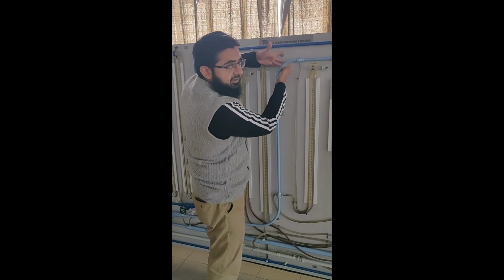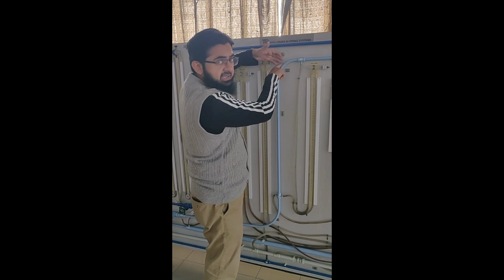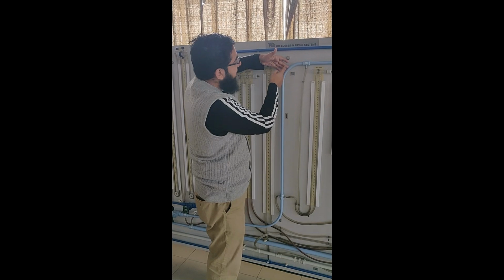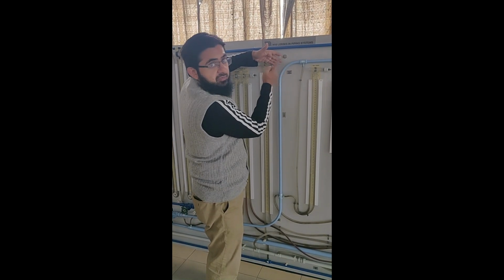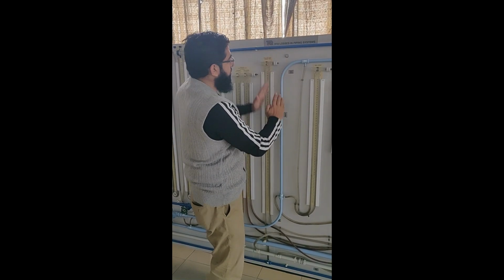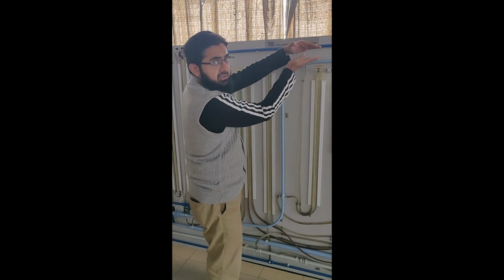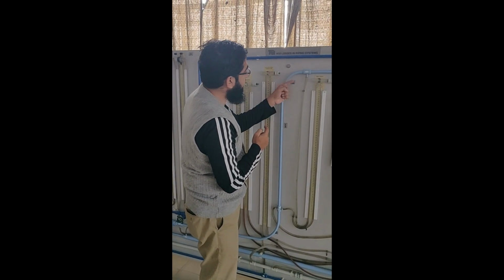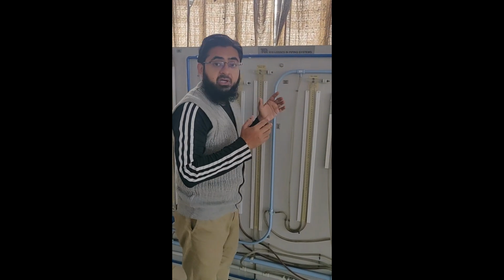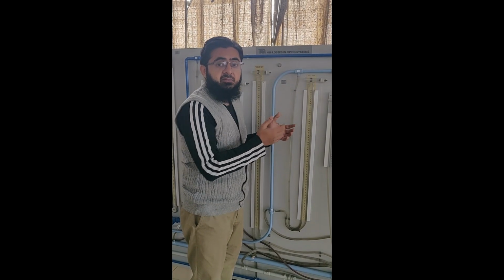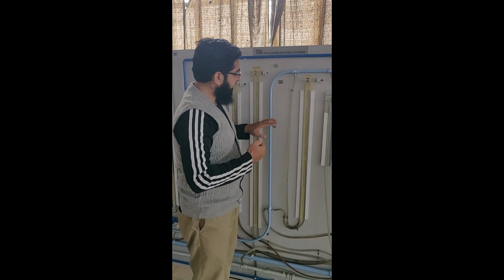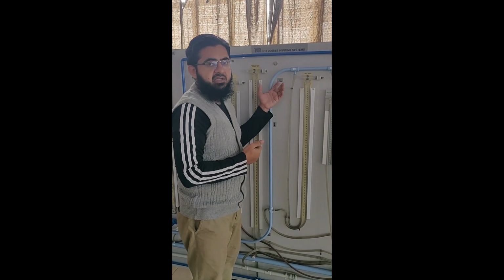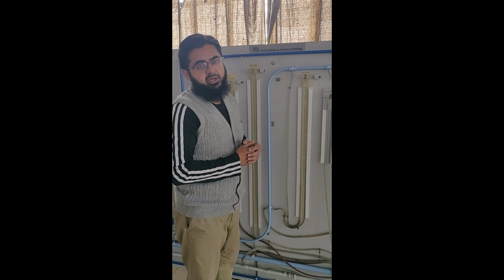The other reason is that there is a difference in pressure between the outer side and the inner side. Because of this difference of pressure, a secondary flow would occur here. So primary flow is in this direction and at the bend, because of the difference in pressure, there would be a secondary flow. Now to maintain that secondary flow, some energy would be extracted from the main flow, and that also causes losses. So these are the reasons for the losses in the bends.